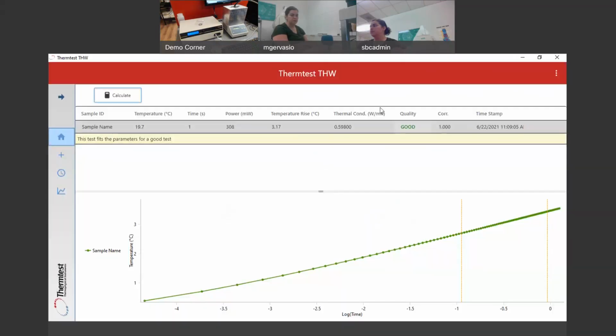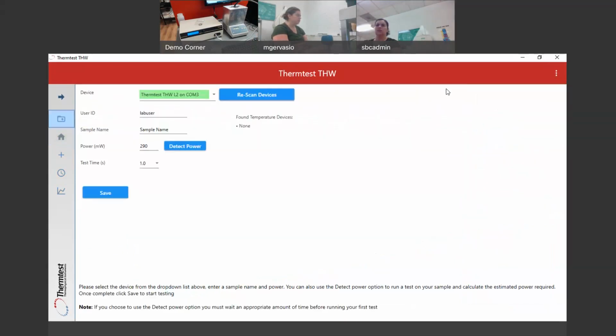You can do this directly, or if you want, you can wait 5 minutes. The reason for waiting 5 minutes is that you already increased the temperature of your fluid. If you see here, there is a temperature rise of 30 degrees. So the temperature is not 19.7, it's 22, 23. So it's better to wait. Usually, especially if it's not inside the bath, it's good to wait 5-10 minutes to stabilize. And then you go again, new sample.